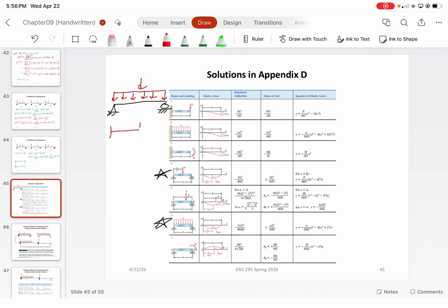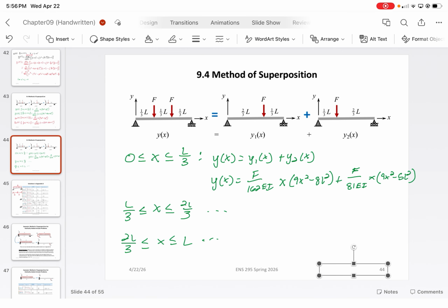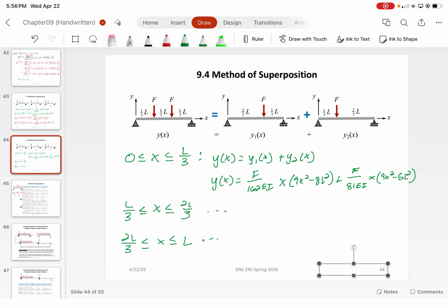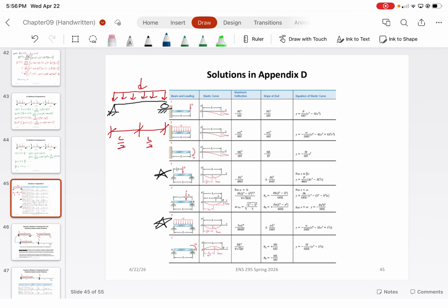And then you've got a point load here, and you want to define what the max deflection in the beam is, as long as the locations of max deflection coincide with each other. In this case, the max deflection of the beam would technically be at that L over 2 point. For both instances, it would just be the summation of those two deflections.